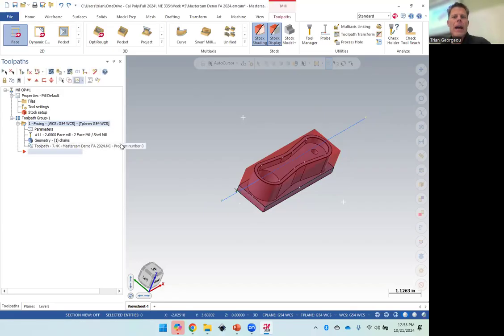Now, what we've got here is a blue line in the way. Do you see that? There's got to be a way to hide those, right? Does everybody see the wavy blue lines next to the ghost? The wavy blue lines hide and show toolpaths. Makes sense, right? The toolpaths are blue lines. It's got three blue lines. So you can hide. Whoops, don't ghost things. Hide and show. I'll talk about ghosts later. It's like suppressing. Ghost is a suppress, basically. They had ghost before suppress was around. This software has been around since 1983.